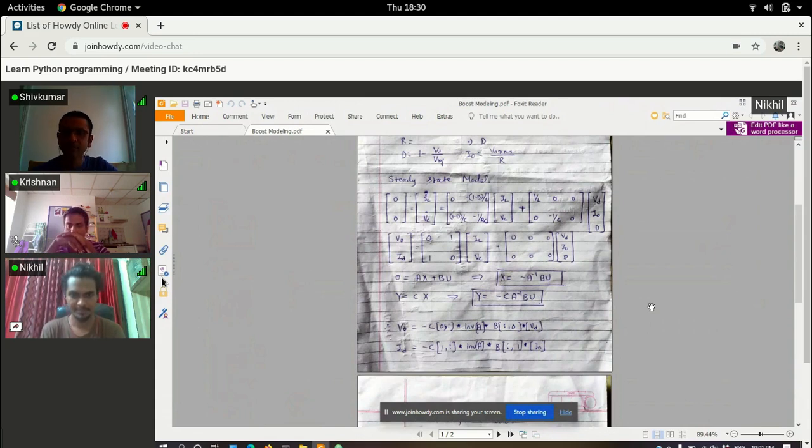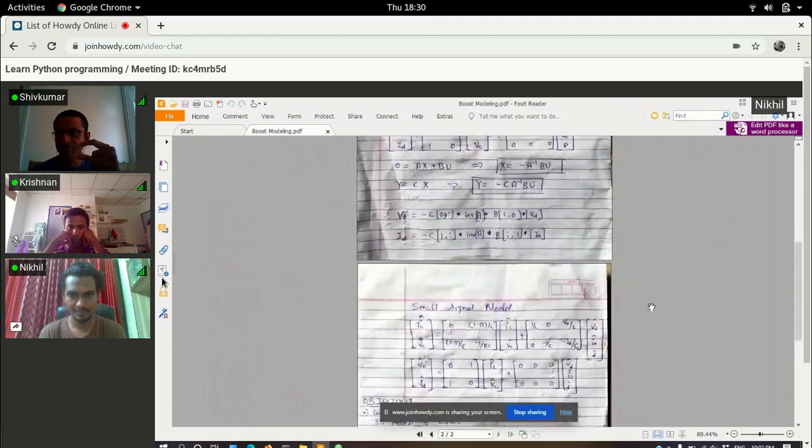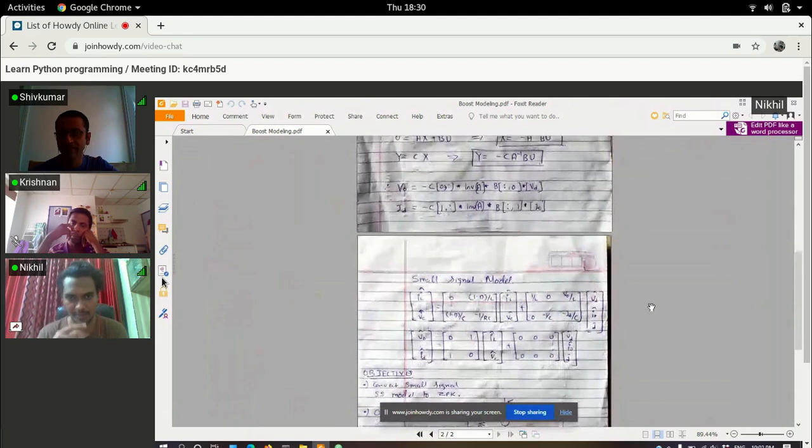But even if you want to do that, all you need is your inductor current. You don't need the output current. You just need a limit on one state variable. So your output variable is the variable of importance that you want to regulate, and the inductor current is merely something that you want to place a limit on. Okay. You don't need to define another variable.